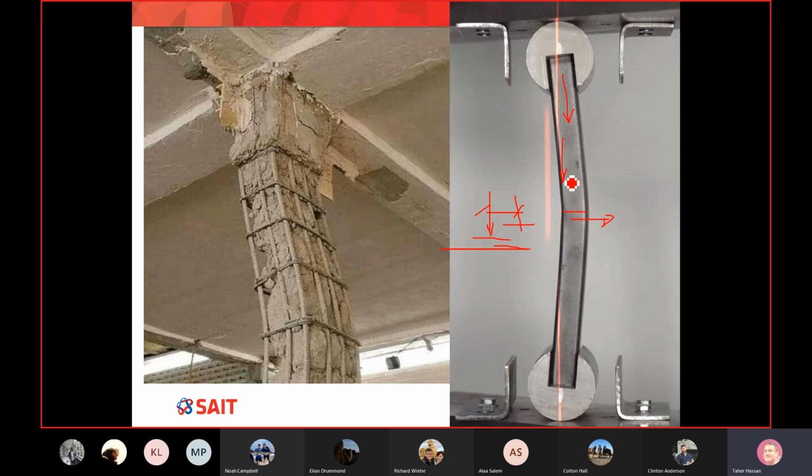So right now, here is my load, here is my section, and you can see there is a distance between the centroid of the section and where we apply the force. You know what happens? This creates a bending moment on the column, and this is what bent your column. So that's why buckling is dangerous. It causes something called eccentricity. It causes deformation. It means that the shape will be deformed.